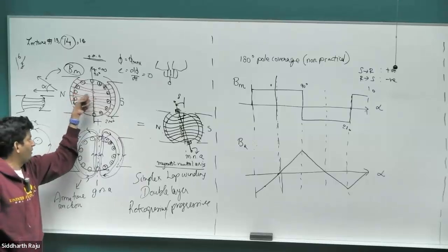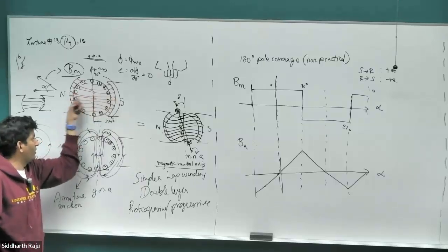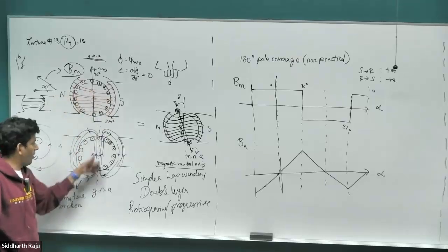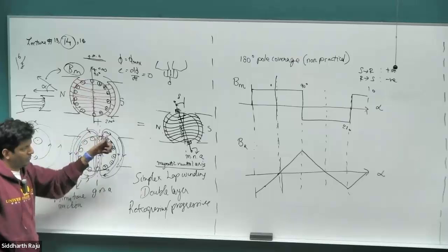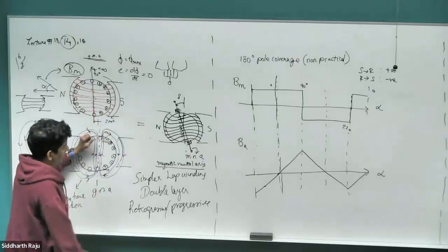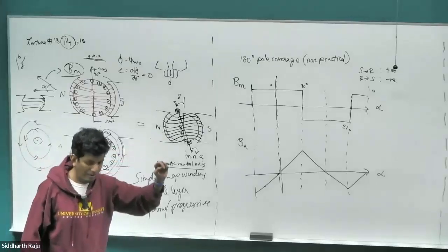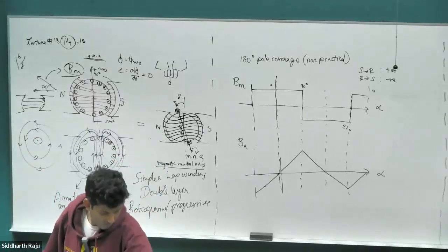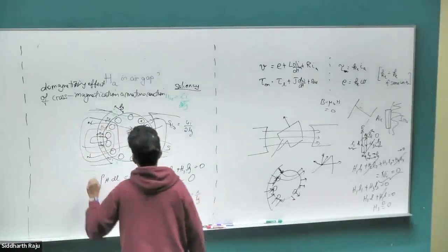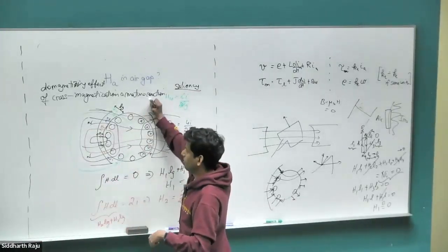Any magnetic field that lies along the external magnetic field, along the x-axis, we are going to call the direct component. Anything that's perpendicular to it, we'll call quadrature or the cross component. So this magnetic field due to the armature reaction has this cross component, but it has a demagnetizing effect as well. Due to pole shift, there will be another demagnetizing field that's induced, which is completely different from this. So the terminology does get a little bit confusing there.